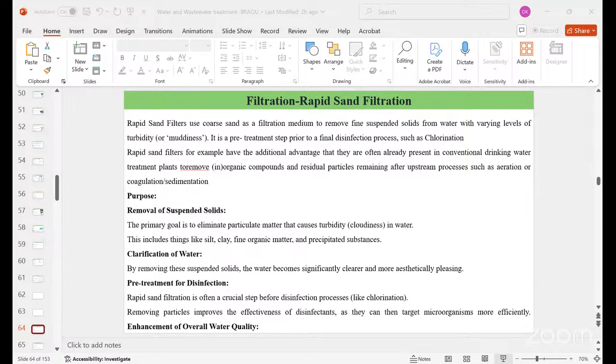The main considerations will be the head loss through the system, and the distribution of water flow should be uniform. Head loss should be minimal or prevented, and the hydraulic capacity should be enough to handle the backwash flow rates. So, the backwash system.